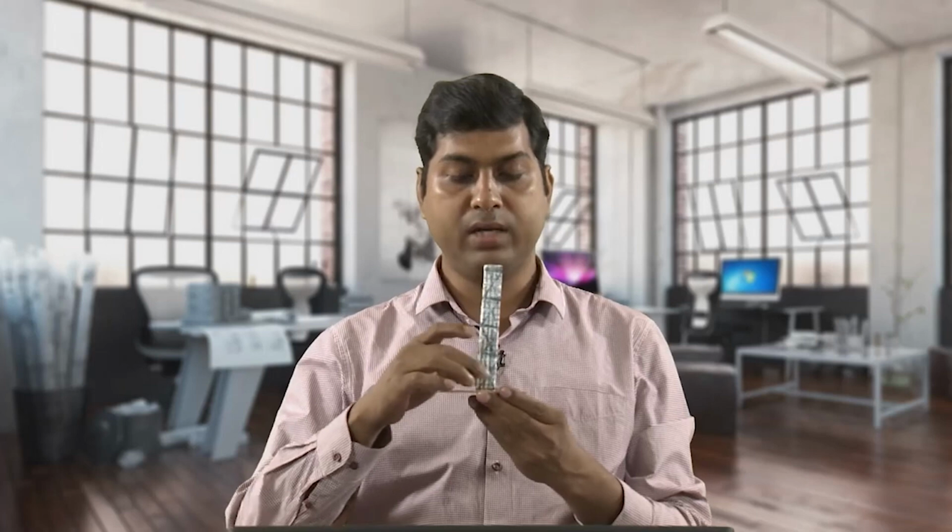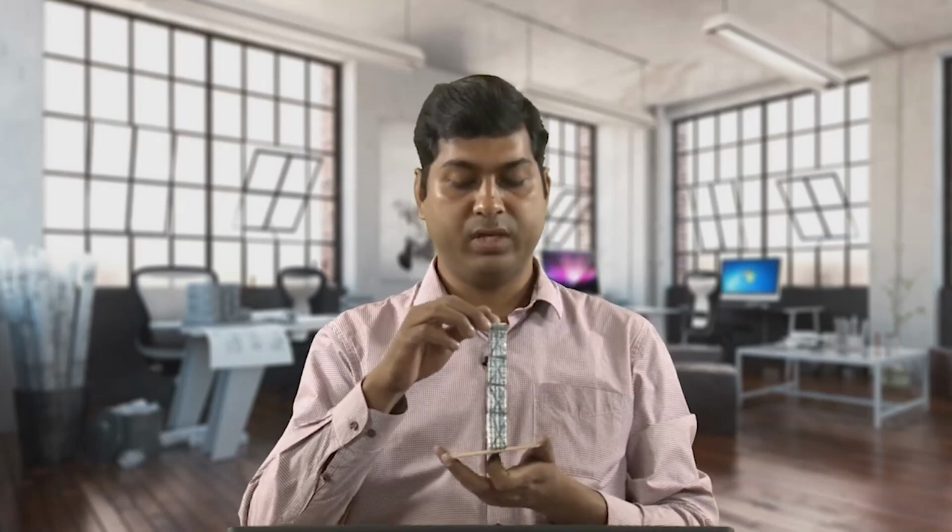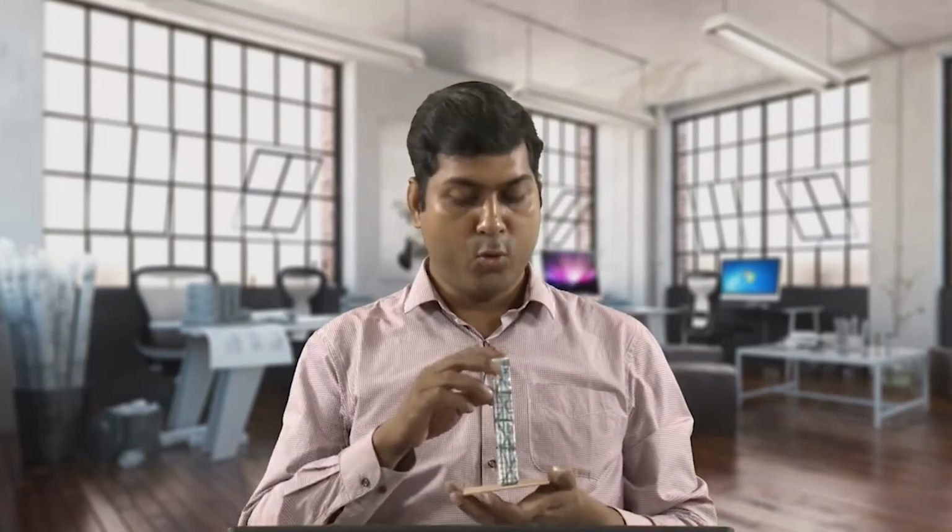I have this building, which is grounded like this. So, during the earthquake there is a random jerk with different intensity. The ground will try to move, but the heavy structure will have inertia, so it will try to stay in its original position. That will lead to sway, and the moment the surface sways in this direction, this part will stay in its original position, and this will create huge sway at larger height. So, it will be vulnerable to collapse.